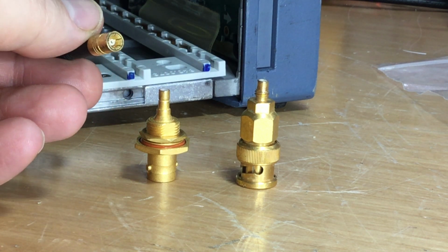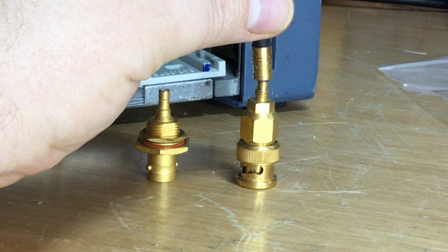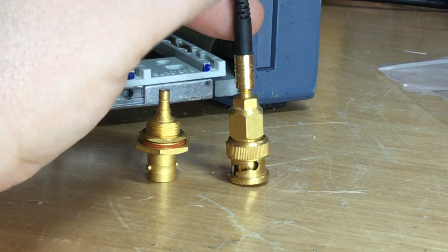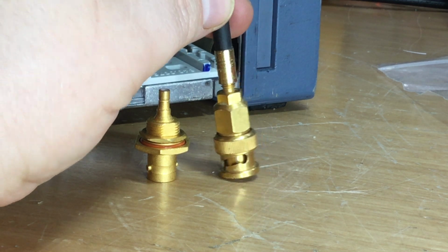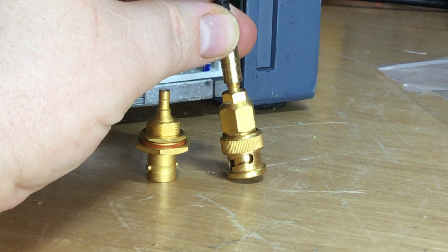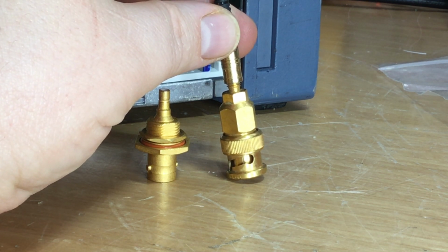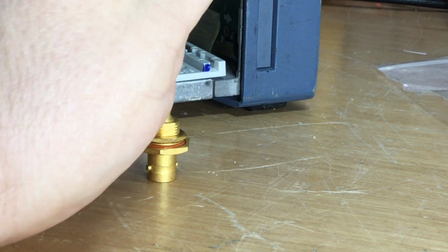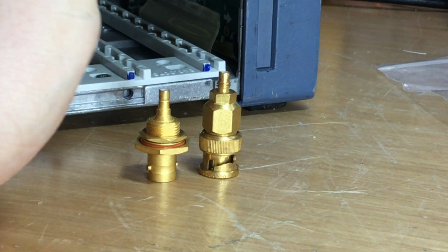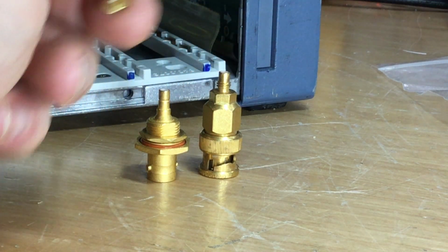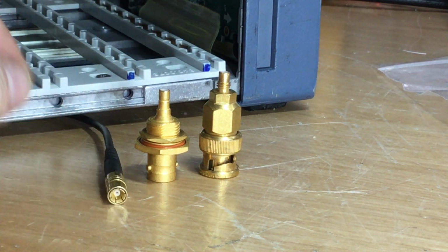Notice we can take the SMB and we can still try and plug it on, and this is where I've seen engineers going wrong over the years. So it partially pushes on, but because of that screw thread at the bottom there, it won't go home. And there's a good reason for that, because it's a wrong plug for that socket. So in order to do that properly, unlike some people I've seen over the years who try and push them on and then damage the plugs and sockets, you need the right tool for the job.